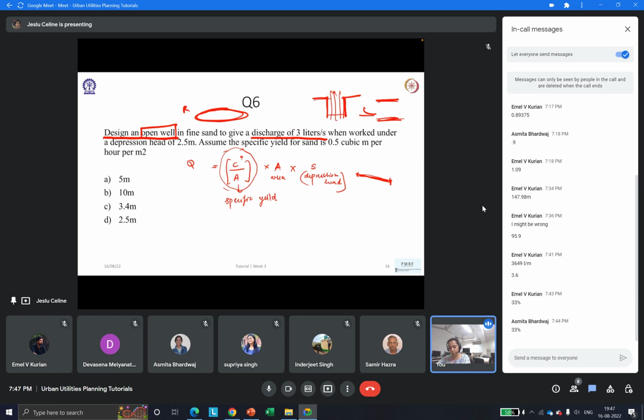The recuperation test means that if you have a normal well, and the water level is this much, we draw water and the water level reduces. Imagine it comes down to this much. Then after a specific duration, imagine after 1 hour we are checking, the height of the water in the well will increase. So to what height is that increasing? We take that information, and that's how we come up to all of this.